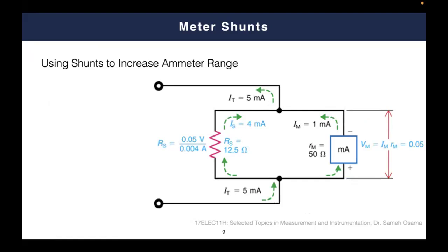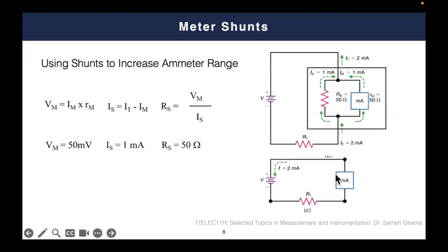So now the equivalent resistance of the ammeter is 10 ohm. If you insert this ammeter in the same circuit, the overall resistance seen by the supply will be R plus 10 ohm, which will reflect on the measurements, because in the first case, we have R plus 25 ohm, while in the second case, we have R plus 10 ohm.